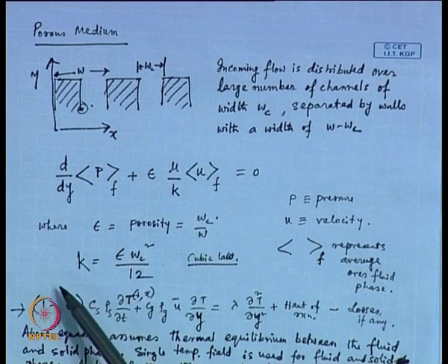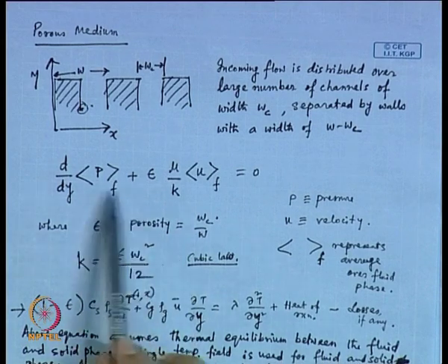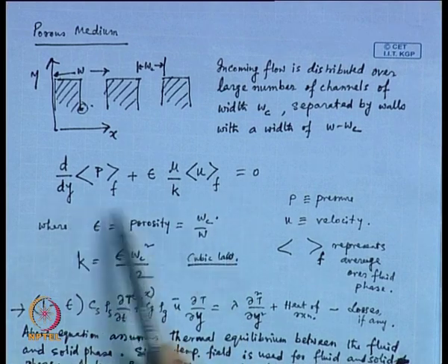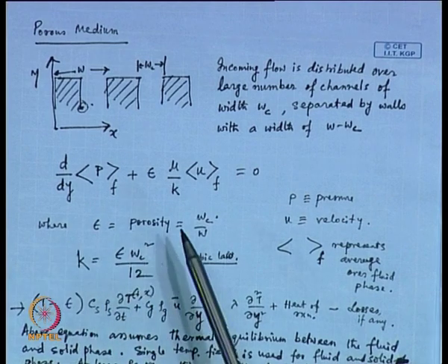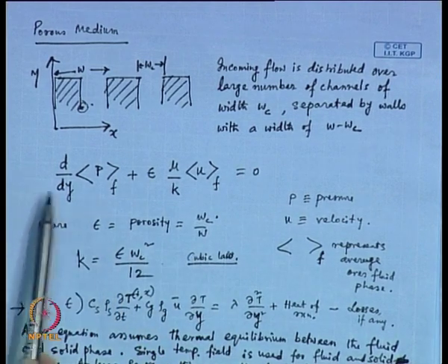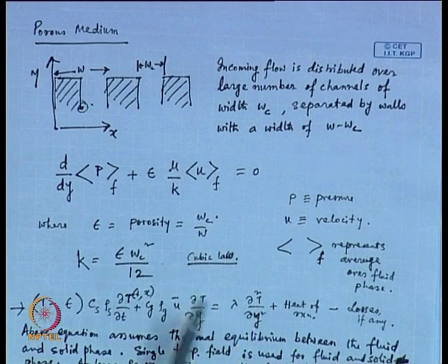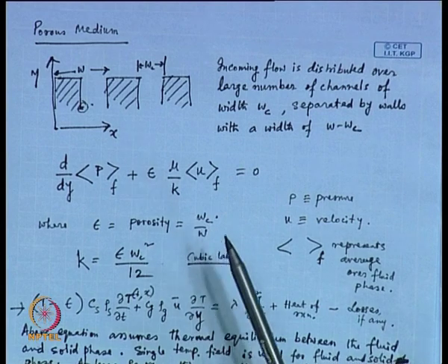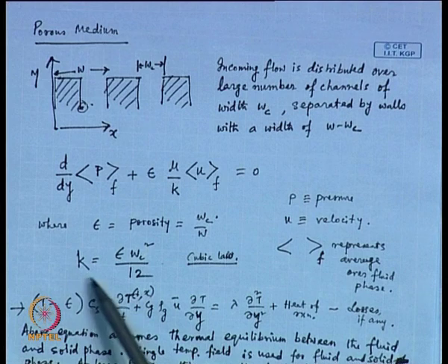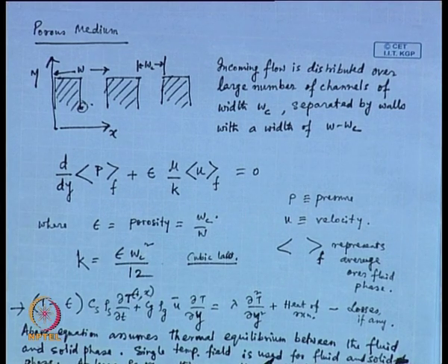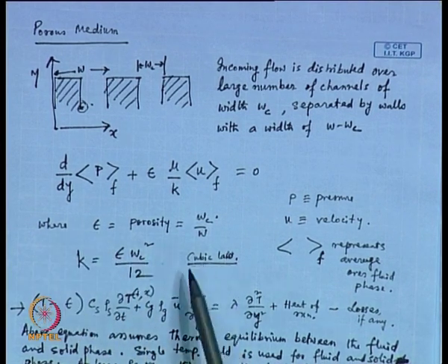There is an expression for permeability, which you can check in Darcy's law, which has been there for quite some time. This will come directly from there. This permeability term in Darcy's law is typically used for porous medium. However, that same equation can be applied for flow through a channel, where permeability can be given as the aperture of the channel to the power square divided by 12. This is referred to as the cubic law.